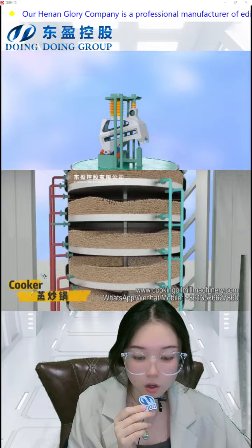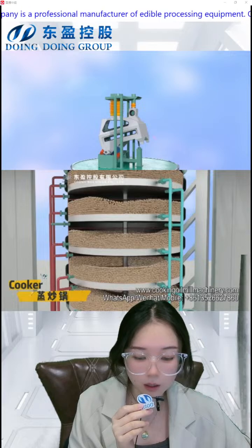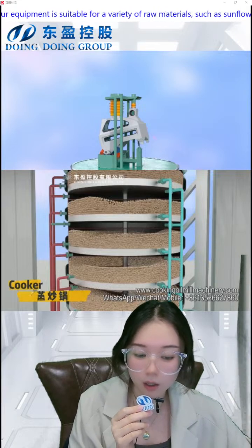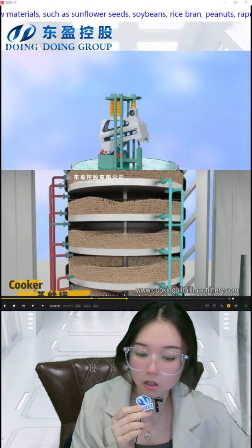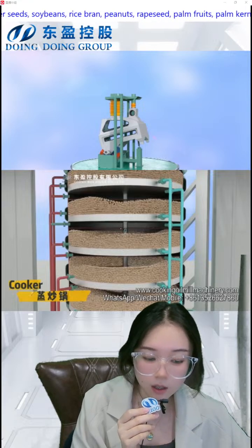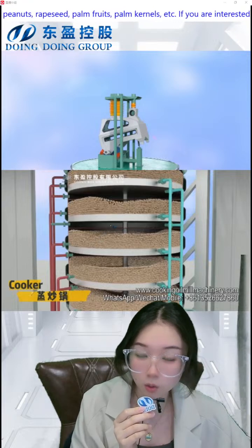It also can control the feeding automatically. The oil seeds processed by steaming and frying can be adapted to the pressure of the oil press, and the oil yield can be increased. The body of the steam cooker is divided into 5 layers. The bottom of each layer and the edge of the cooker are steam interlayers. Each layer has a valve to adjust the steam entry in order to control the temperature.